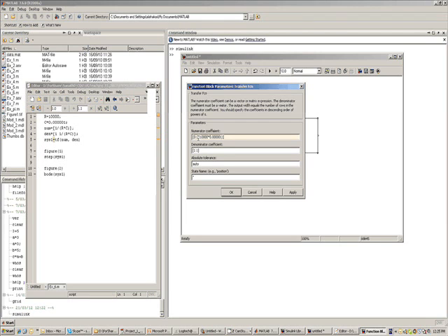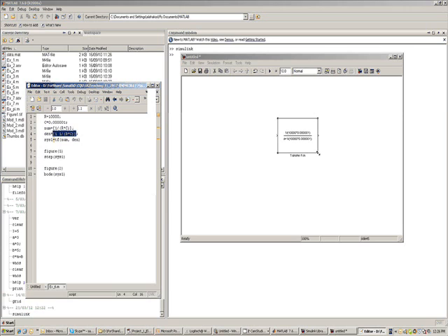And then I'll do an easy thing. If I just copy and paste 1 upon RC as the second coefficient, the coefficient of the constant term, into the denominator polynomial, I have now typed this value into the transfer function. Now if I apply and close it, you can see those values have been assigned to the transfer function. So now we can use this block to find out the step response.